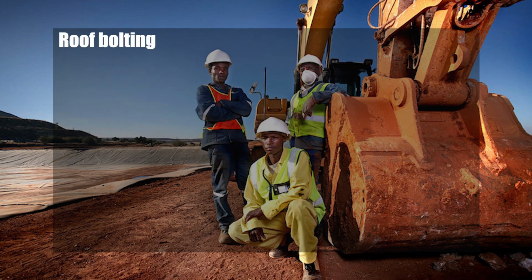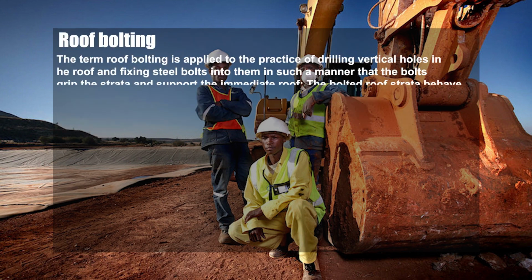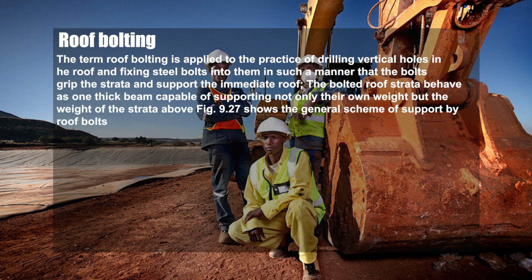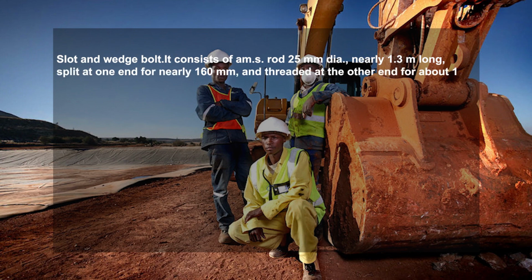Next is roof bolting. The term roof bolting is applied to the practice of drilling vertical holes in the roof and fixing steel bolts into them in such a manner that the bolts grip the strata and support the immediate roof. The bolted roof strata behave as one thick beam capable of supporting not only their own weight, but the weight of the strata above. The general scheme of support by roof bolts: first is slot and wedge bolt.